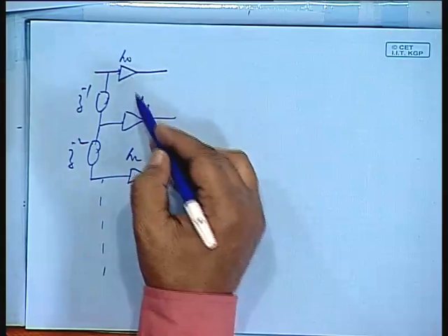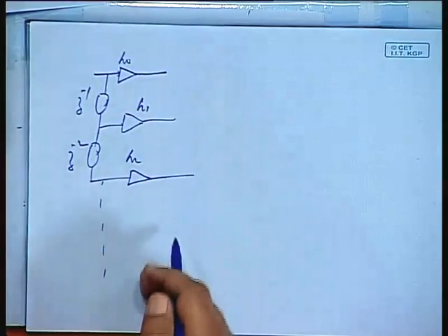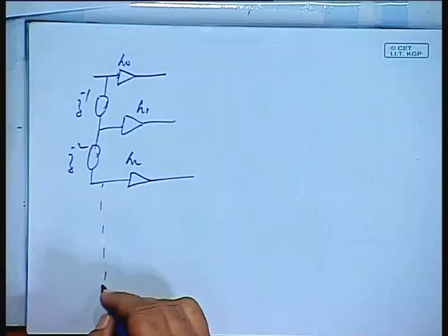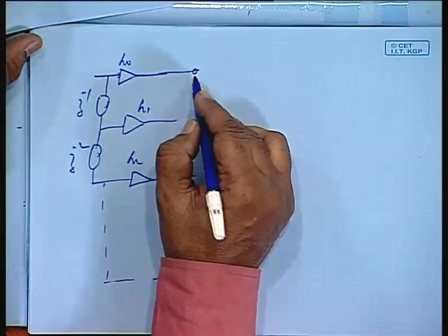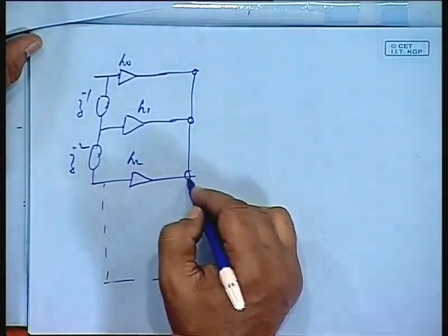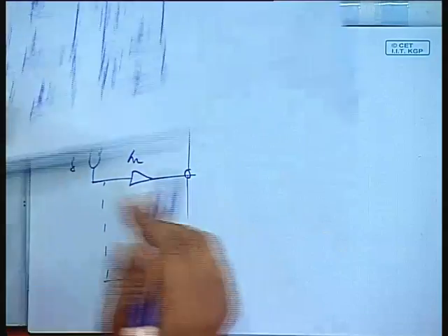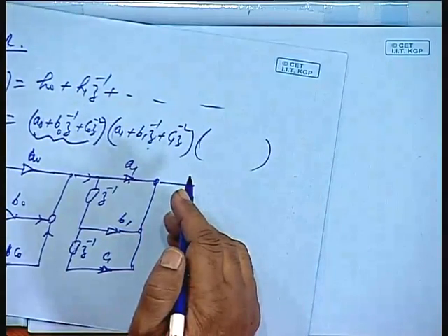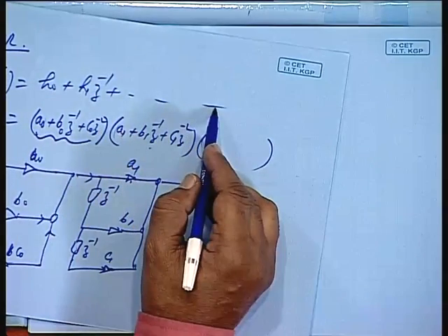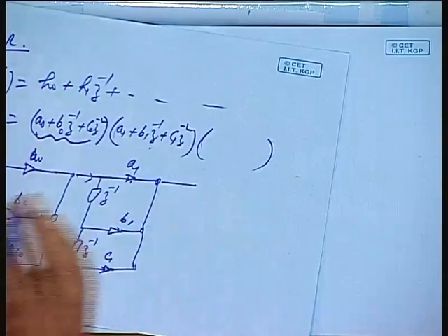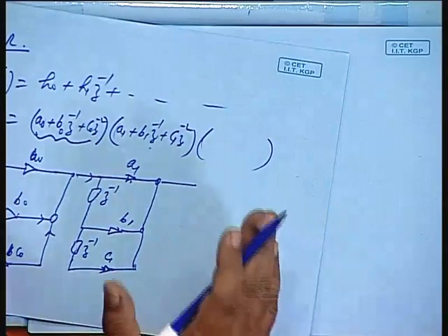Only thing probably this will be easier to implement, it might appear, okay, but then change in any of these will be affecting all the roots, okay. If any coefficient is affected then all the roots will be affected simultaneously. So, here the sensitivity can be restricted to only a limited number of parameters, limited number of coefficients by this realization.